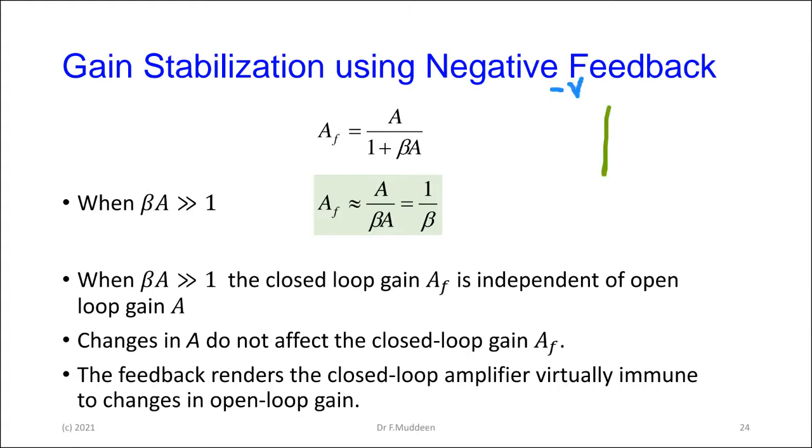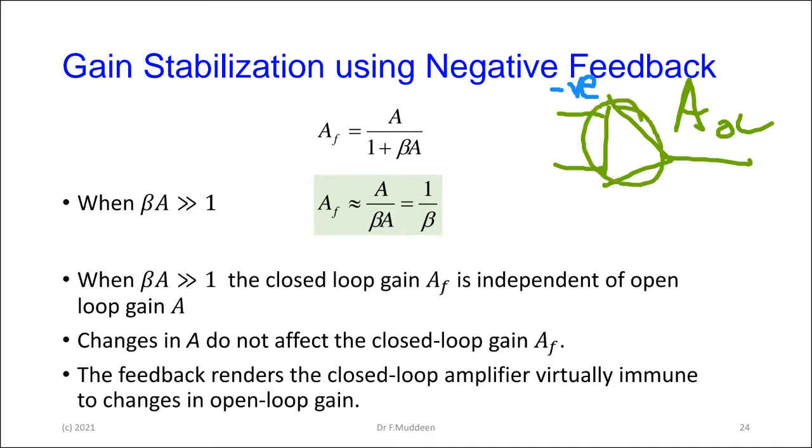So you remember an amplifier, you have an op-amp, for instance, and the op-amp comes with an open loop gain with it. If that gain now, depending on if the temperature of the op-amp, for instance, changes, or the parameters around the op-amp change, that open loop gain may vary. So what we're doing now, if I supply feedback to the op-amp, like a normal inverting amplifier, for instance, we saw that sketch before, is a feedback amplifier.